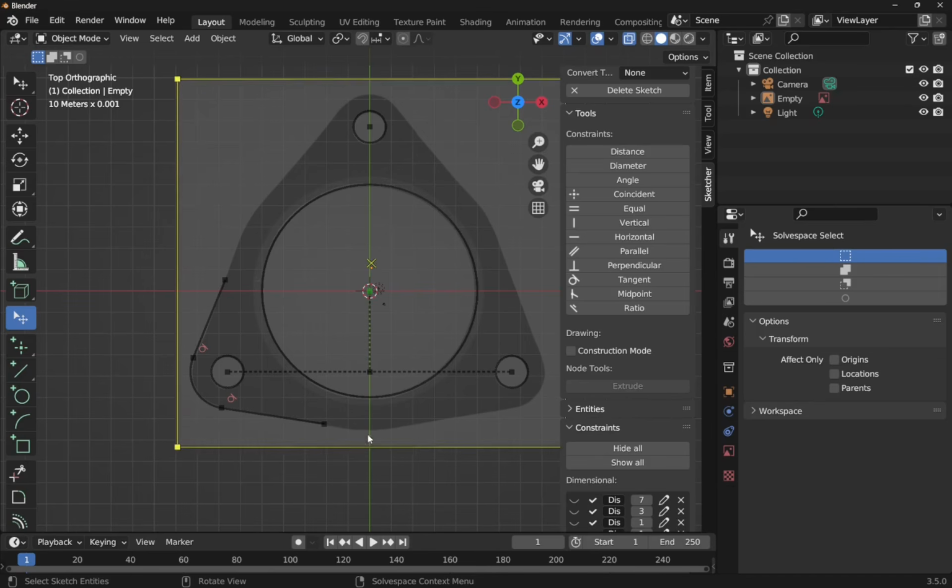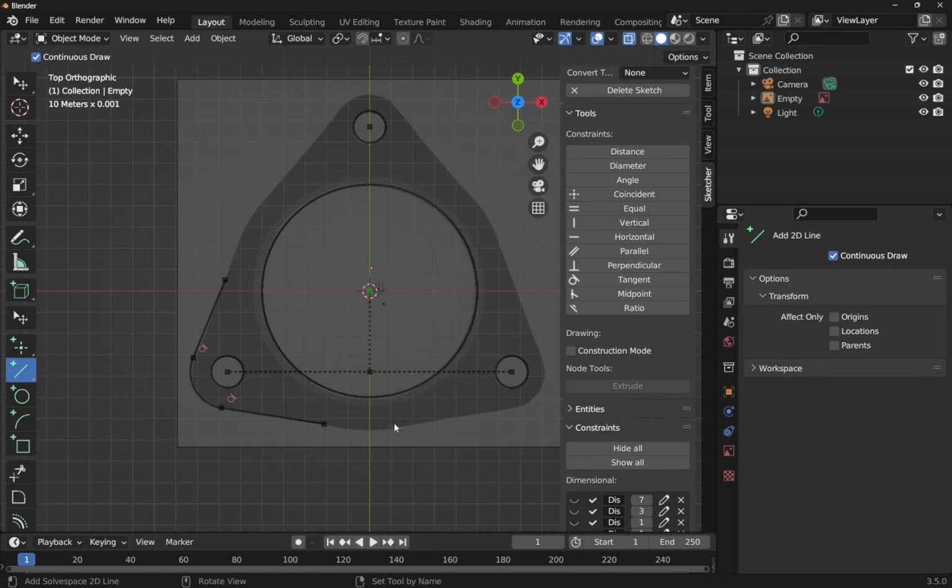So the next thing we need is this arc here. I'm going to make it easier on myself and add the same arc here first, and then we'll connect up in the middle. So let's add the line first. Let's work backwards. So we need a line from about here to here, and right click to cancel, here to here, right click to cancel again, add the arc.